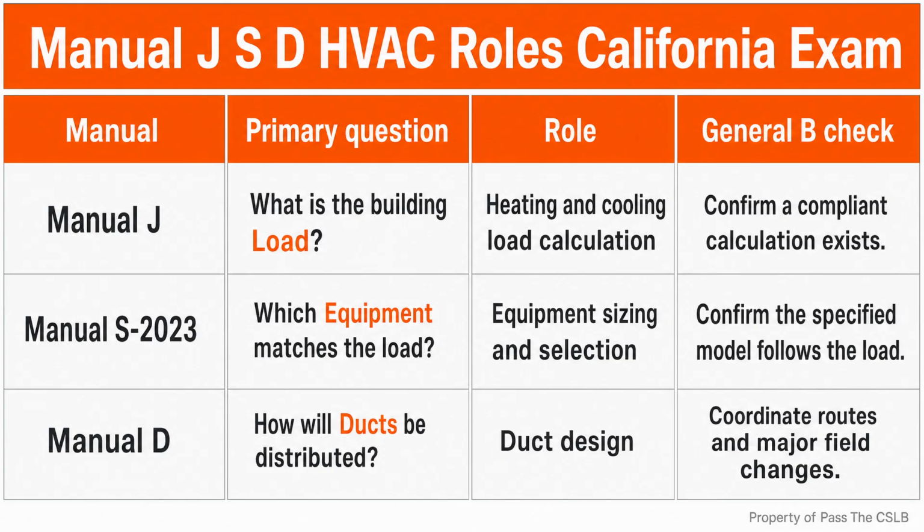Oversizing is the most useful defect recognition example in this lesson because the complaint can sound backward. The house may cool quickly, yet the customer is unhappy. An air conditioner handles sensible load and latent load. Sensible cooling lowers the air temperature. Latent performance addresses moisture. When an oversized system has more cooling capacity than the building needs, it can pull the temperature down rapidly and satisfy the thermostat after a short run.